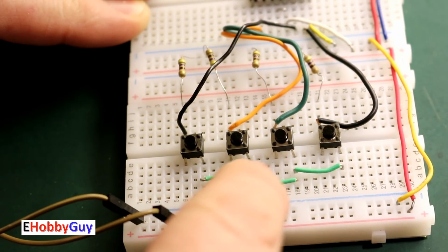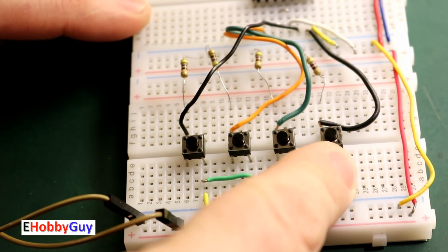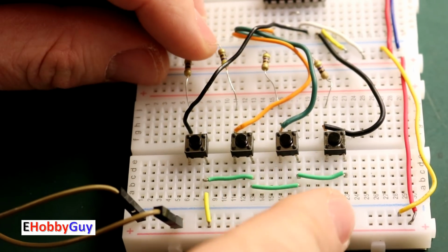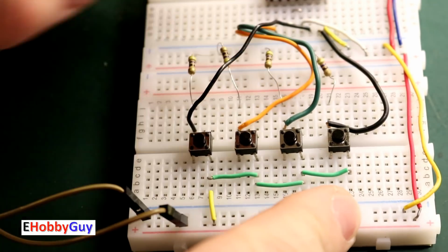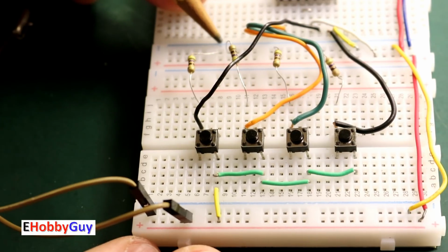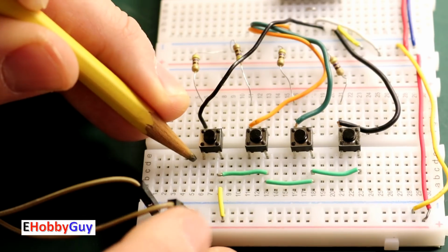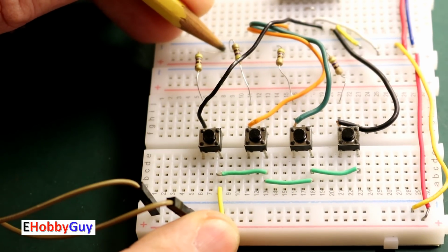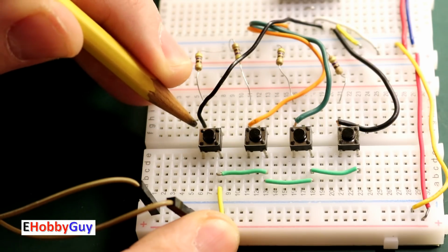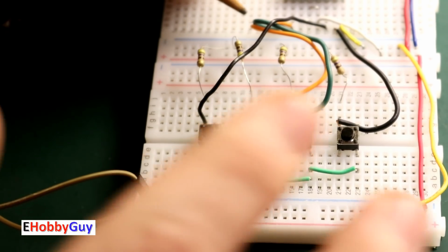I'm jumping 5 volts to each of the buttons. So on one side we have 5 volts on this button. Each button on this side has a pull down resistor. I'm using 470 ohm resistors as pull down resistors. Each one of these are going to the negative rail right here. Here's the blue for negative, red for positive. I'm going positive to one side of this opened momentary switch, and I'm pulling it down to ground with a 470 ohm resistor on this side. Now we're taking this low side and jumping from here to each of the A, B, C, D inputs. Just wanted to make that clear.